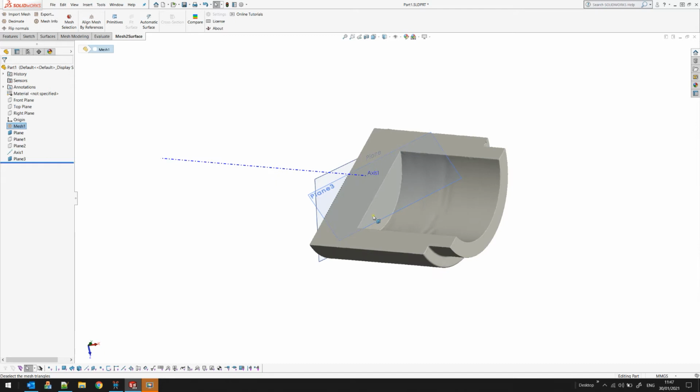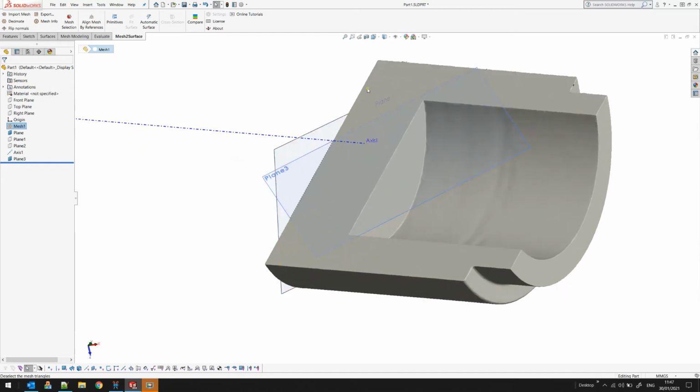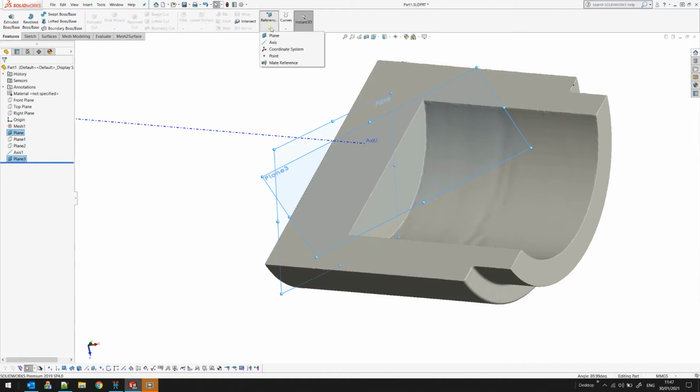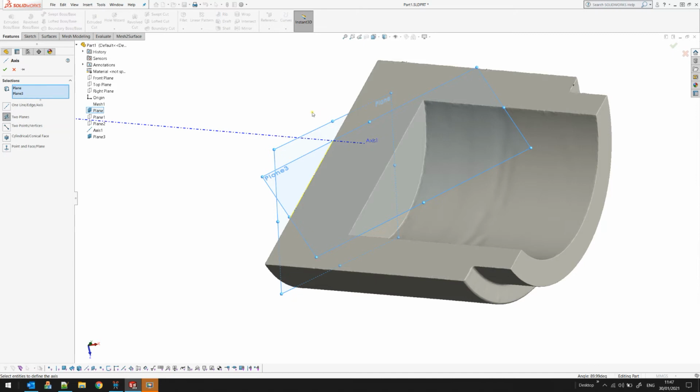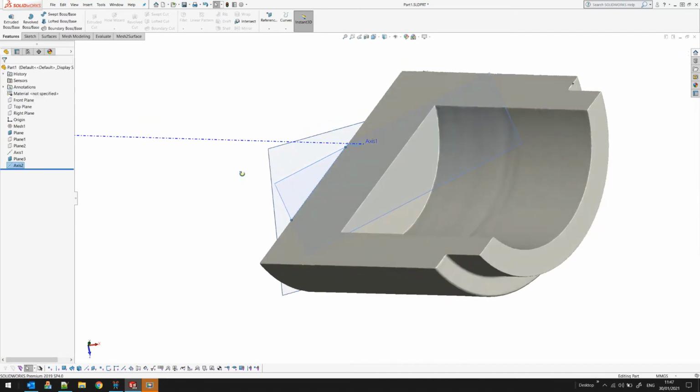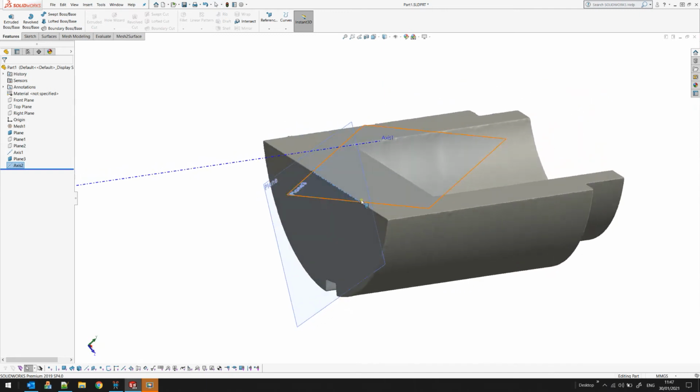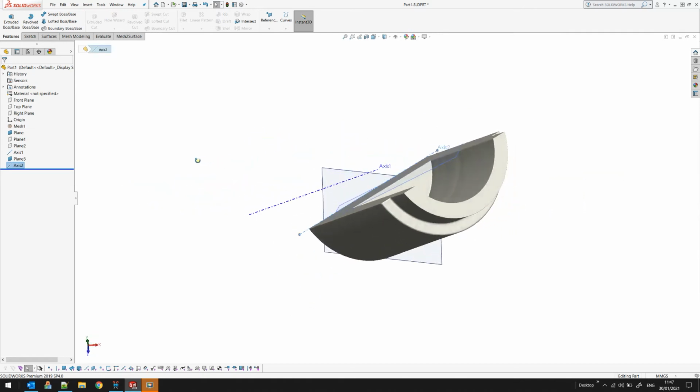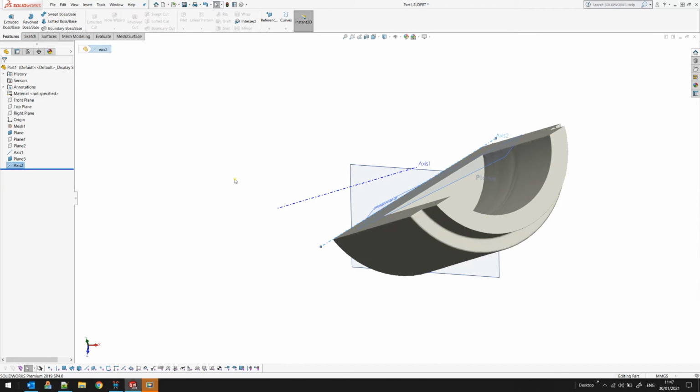The next step is to extract this line, which is the intersection of the two planes. For this, we will just use the standard SOLIDWORKS command. I will select one plane, then using Control, select the other one. From the features, I will create my line that is an intersection of the two planes, and I can press OK. Now we have all we need to move on to the next step, which is to define our coordinate system that will align this object properly in space.